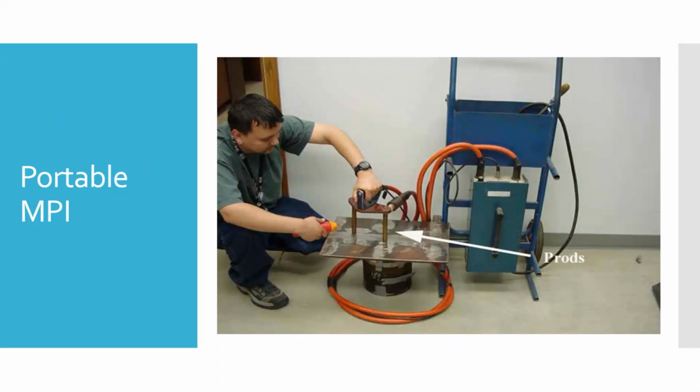And so many of you said, if you take a magnet and you do the iron filings, they end up in nice little arcs going from the North Pole to the South Pole. What do you think happens if there's a crack? What's it going to do? It causes some kind of an interruption to those nice little arcs. You'll see like a weird pattern or something along those lines.